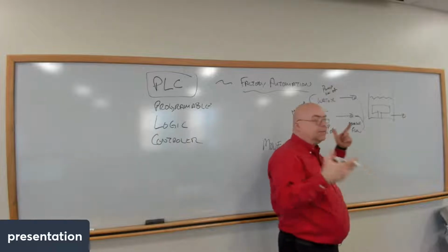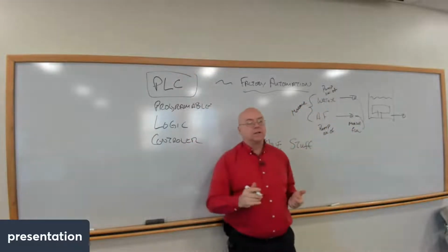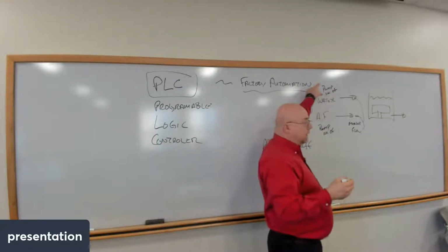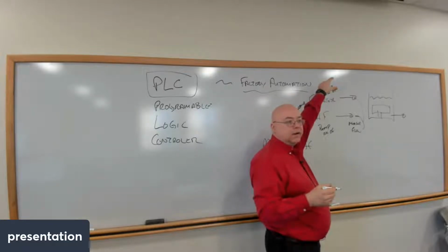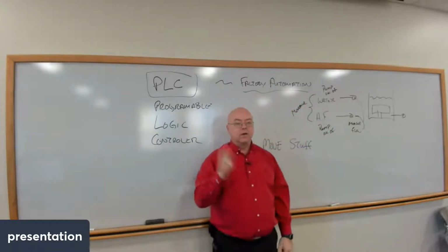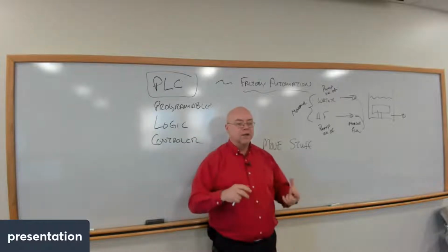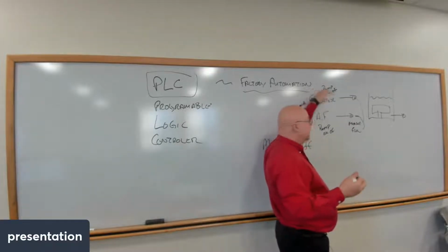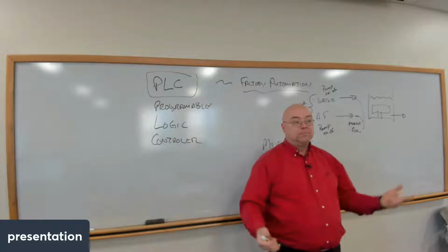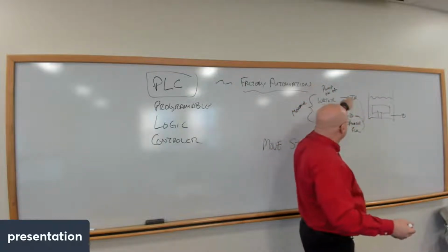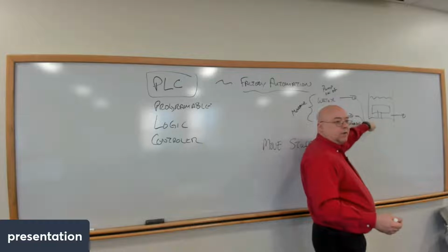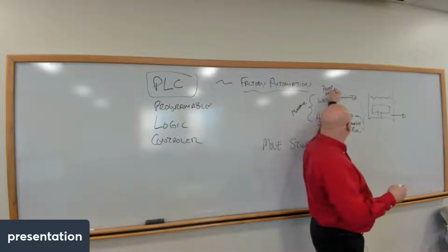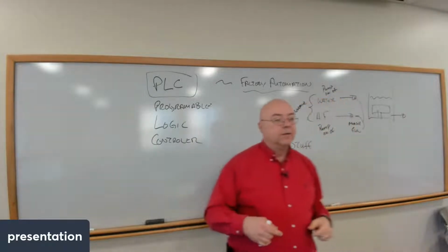And so if you didn't have a PLC, you didn't have a system to do this, we could still control this. We could have a relay that controls the pump. A relay is just when it gets a signal, it turns on, gets another signal, it turns off. So it's a remotely controlled switch. We could have a relay that turns the pump on when somebody presses the start button, maybe. Start the pump. And then we have a sensor over here that's monitoring the flow. And when it measures the correct amount of flow, it can send a signal back to the relay to turn it off.